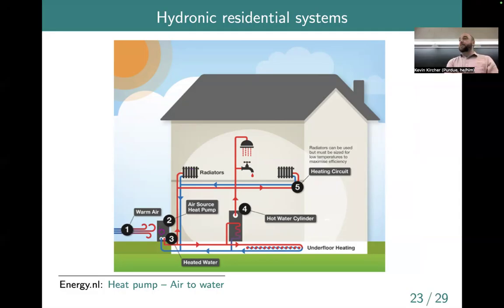Sometimes you'd have one piece of equipment that would provide hot water both for space heating, but also for domestic hot water uses: showers, baths, dishwashing, things like that. So you could imagine running some of the hot water into a tank, which then could feed showers and baths. And this isn't very common in the US, but in European buildings it's more common to have underfloor or slab heat, where you'd have a heat exchanger in maybe the concrete floor, and then you'd get nice radiant heat coming from below.